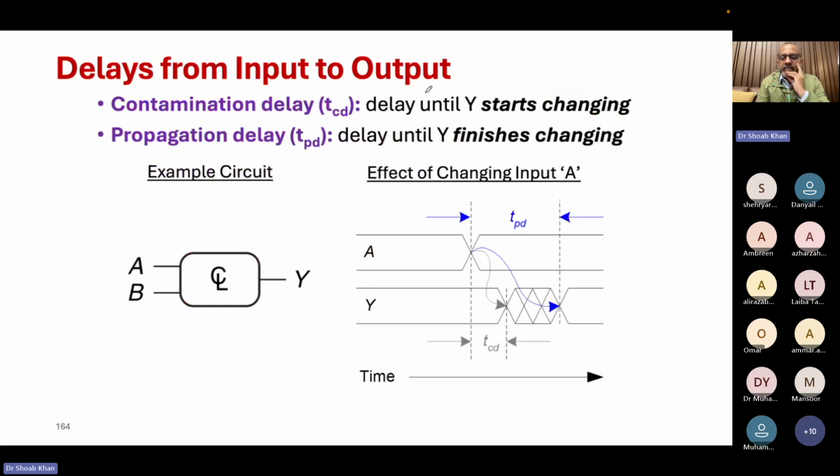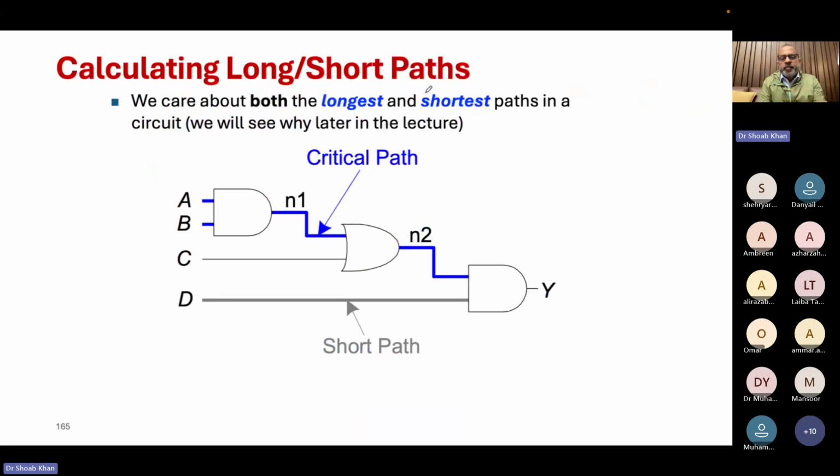So all these delays, and why there are delays, this is important. You see that this is a logic, this path is going through, and that's why I told you to trace all the paths. There's a path which is going through only one comparator, then a path going across two comparators, then three comparators. The path which is only going through one comparator or one gate delay will have some stable value, but the second value is coming from here. This is the second path. So based on this value and this value, whatever was there, it will switch.